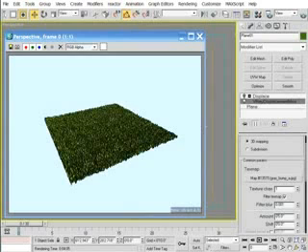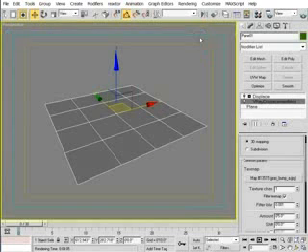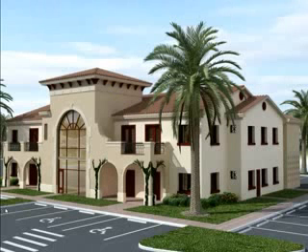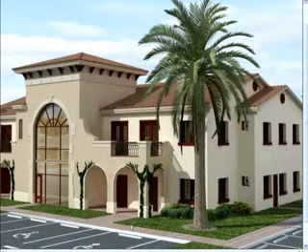this is what I get. A really nice and quite realistic looking grass. Notice that it did take some time to render this, but in my opinion it's well worth the wait. One of the great things about using the VRay displacement modifier like this is the look that you get when a grass object butts up against another object such as a road or a curb, and where it does join, the two objects won't appear to have a straight, unrealistic line. It will be more of a jagged line like the one shown here in this image.